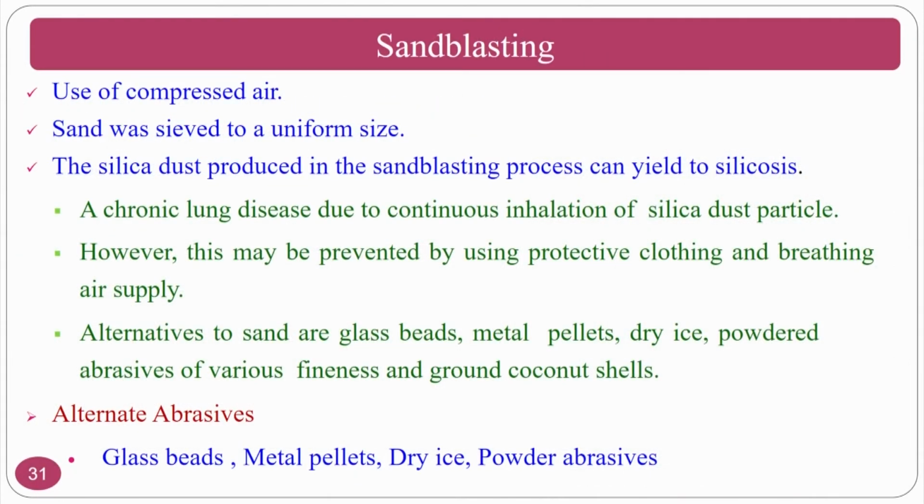Sandblasting uses compressed air, and at the same time you take the abrasive particles and sieve them as per your requirement, the size that you want and all those things, then you use them in sandblasting. Basically sand is silica, or silica dust. The basic problem with this is the silicosis problem. This is a chronic lung disease due to continuous inhalation of silica dust particles, because you are sending high pressure gas along with the silica dust, that is sand.